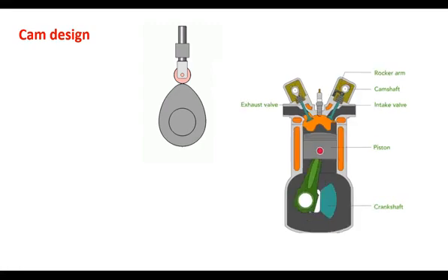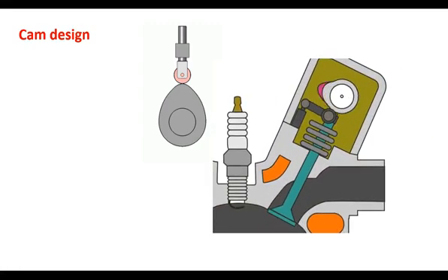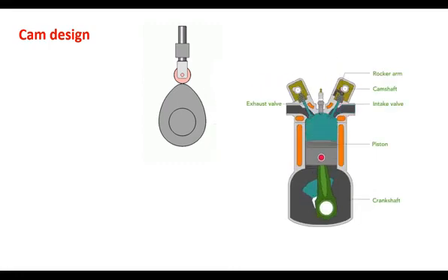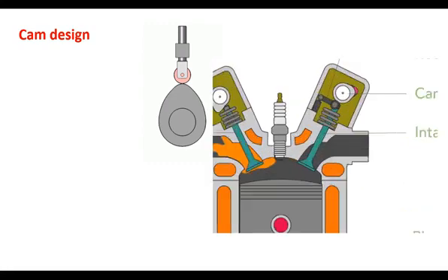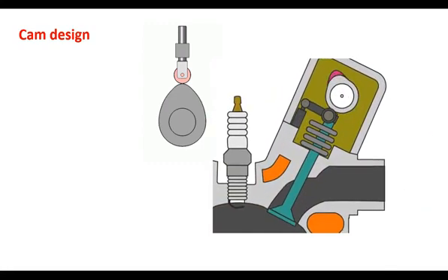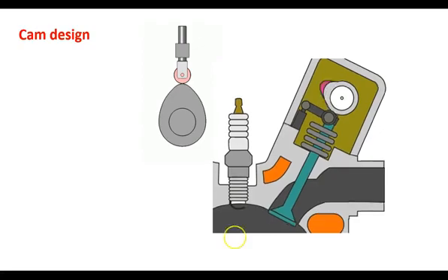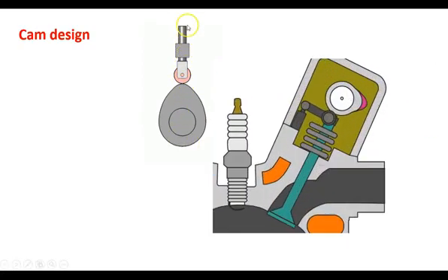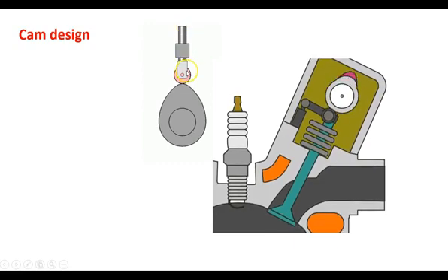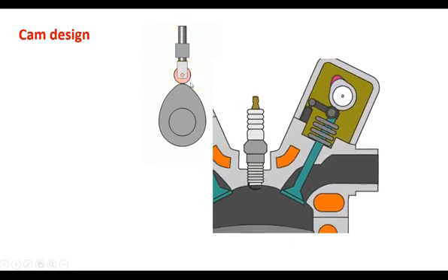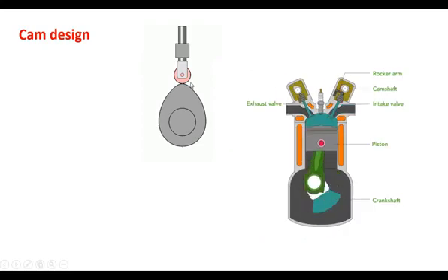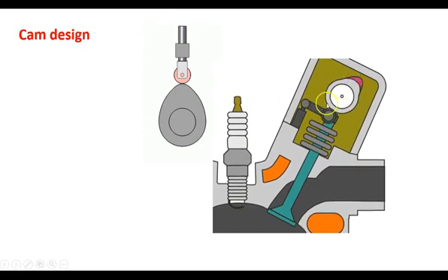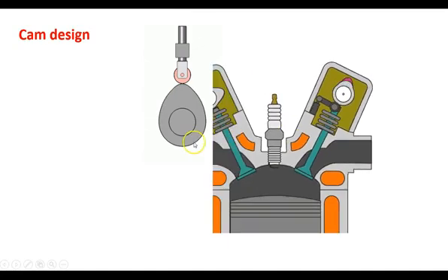So this is just a very basic cam that I just brought up. As you can see, in this case it's most likely steel, though it could be other types of material. The cam rotates around, and there's this lobe at the top, and you've got this guy at the top riding on the cam, and that is known as a follower. Again, that's the whole purpose of a cam. It's a mechanical device that converts rotational motion into linear motion. Rotational motion, linear motion of the valve.